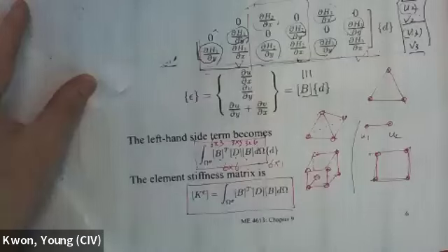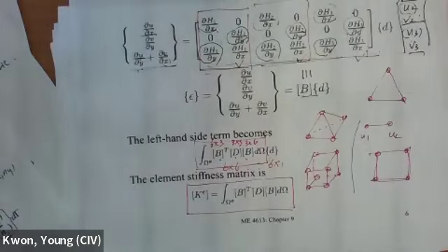All right. So if you imagine what the commercial code does for your solid mechanics calculation. In other words, I'm going to do this stress analysis using this type of element. If you provide a mesh, then they know immediately this is going to be 1D, 2D, or 3D. And then you select, I'm going to use this type of element, and I'm going to say this is the linear elastic isoparametric isotropic material.